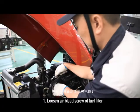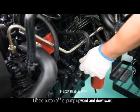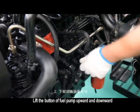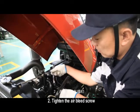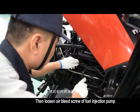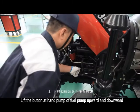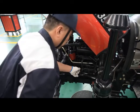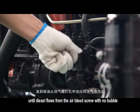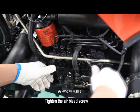1. Loosen the air bleed screw of the fuel filter. Lift the button of the fuel pump upward and downward until diesel flows from the air bleed screw with no bubble. 2. Tighten the air bleed screw. Then loosen the air bleed screw of the fuel injection pump. Lift the button at the hand pump of the fuel pump upward and downward until diesel flows from the air bleed screw with no bubble. Tighten the air bleed screw.